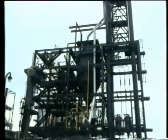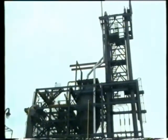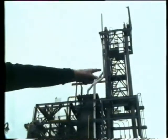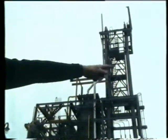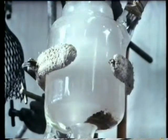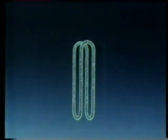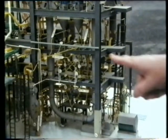We'll have a look at the plant used to make the polymer, or rather, first of all, at a scale model. The polyethylene is produced from ethene in this wide piping. This corresponds to the glass vessel in our laboratory process. Industrially, the glass flask becomes a long metal tube, but in order to have a sufficient volume, this would have to be inconveniently long. It could be made into a circle, but this would still take up room. So it's actually coiled up like this, so that we have a long length of piping in a reasonably small space in which the polymerization reaction can take place.